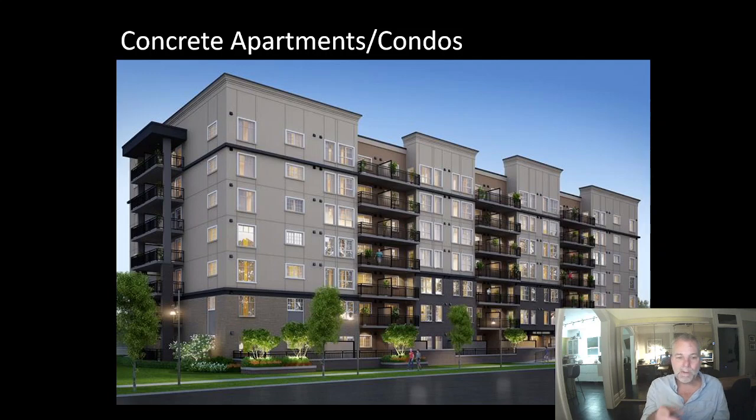Number two is we can introduce thermal breaks. So we can put a thermal break where the balcony meets the building envelope. If we can put a thermal break there, great. Trouble is there's only one commercially available thermal break that I'm aware of, the Schöck thermal break, and it's very expensive. So that's a problem that we need to solve as a building industry: effective, cost-effective, simple thermal